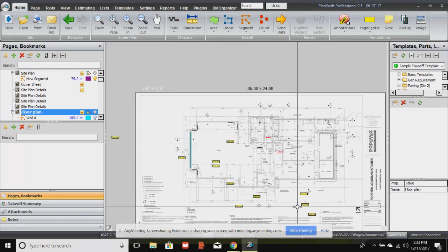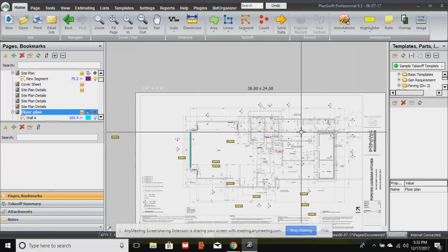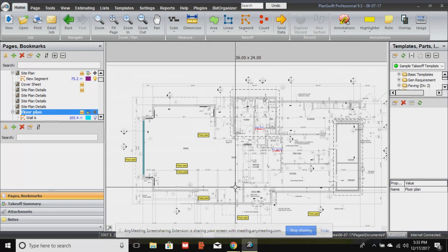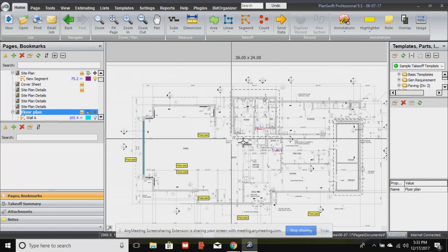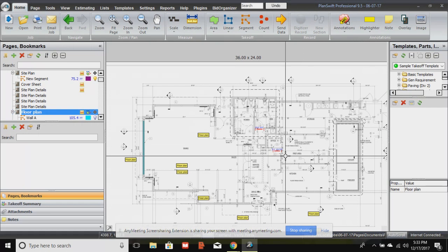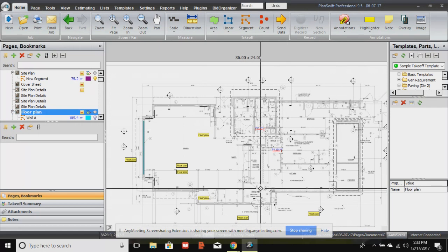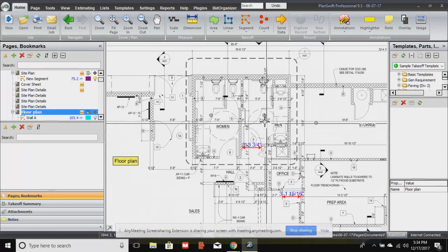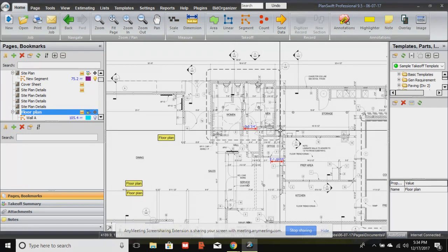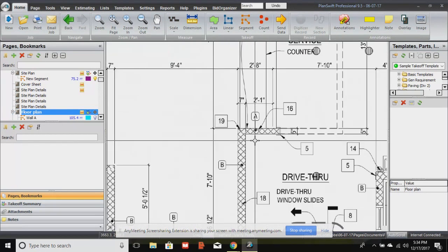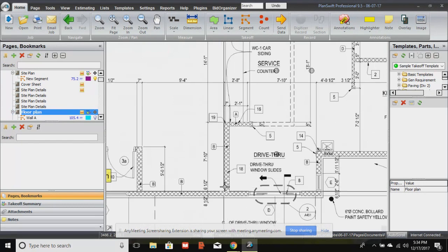All right, so now plan view. We're still on the most basic of the views. We went from a site plan to a floor plan, and our floor plan, same thing. Most basic of the views, it gives us a good idea of our wall construction inside our project, but there's a lot of things we don't get from a floor plan. We don't get any detail. What we're looking at is basically outlines of what is indicated as walls, right? All of these are the new interior walls, and these are the exterior bearing walls that are going to be built. And so we're looking at the plan view of that, and we can use the measurements on the plans in order to take actual measurements of these walls.